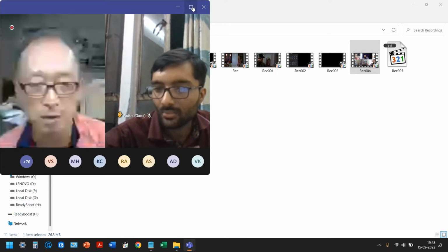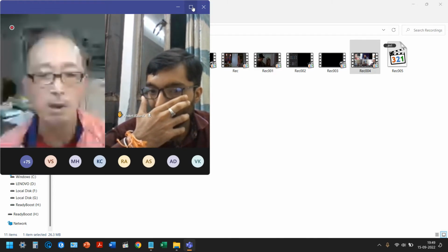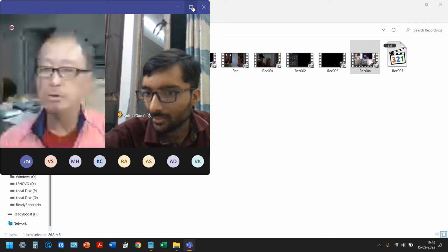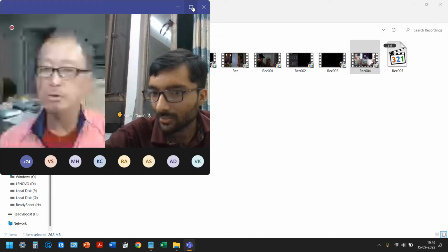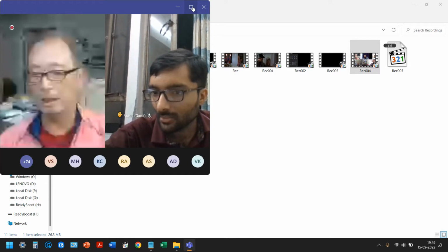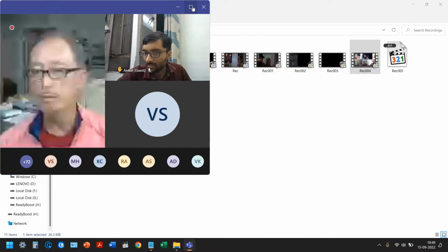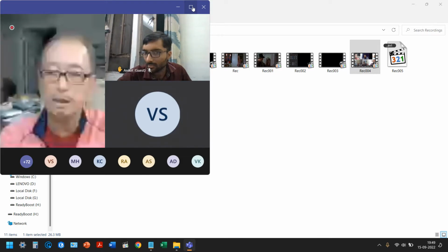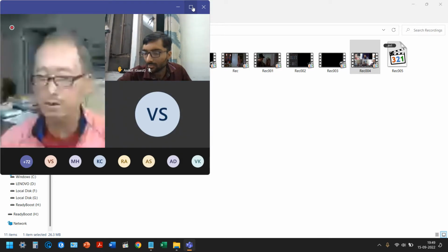And number three, can you comment on the applicability of full waveform inversion algorithms to this setting? Yes, this is a very good question. Full waveform inversion is based upon using your raw seismic waveform data as a signal. You don't go through the subsequent dispersion analysis or inversion analysis.